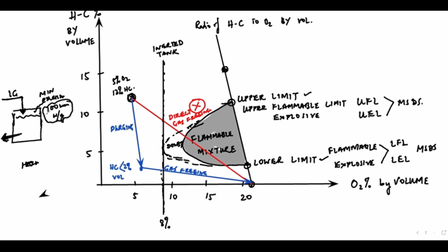Yes, sir. And this is in the inerted condition. Yeah, of course without inerted condition we will not be discharging cargo, and if you are talking about some vegetable oils and all, that is not petroleum product. Inert gas does not apply to that. Okay? So that is how it needs to be maintained.